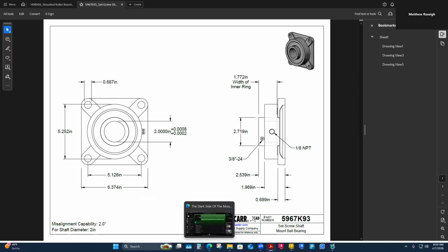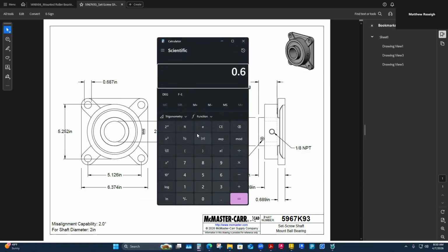What I'm tripping out on, you guys, is that if I bring up my calculator, this is 0.687. If I put a 1/2 inch major diameter screw thread through here, it's that big. It's almost 3/16. I'm going to divide this by 2 because that's what you'll see all the way around it. It would have like 90 thousandths, 93 thousandths clearance all the way around a 1/2 inch bolt through a 0.6875 hole. That's what I would call a sloppy fit. So maybe I might rethink this and say, I think a 5/8 fastener might be better. That's pretty big.